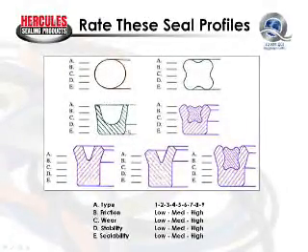Here we have a seal profile that would be typical of a pneumatic cylinder. Relatively thin wall lips. We have a square profile where the height of the seal is the same as the cross-section of the seal. Because of the thin wall lips, we probably would rate this seal maybe about a 3 on our continuum. Because of that, our friction is going to be somewhere in the low to medium range. Our wear is going to be low to medium. The square profile is medium profile from a stability standpoint, so stability is going to be medium. Our sealability, we're down in this area here, low to medium. Okay, but that typically is adequate for a pneumatic cylinder application.